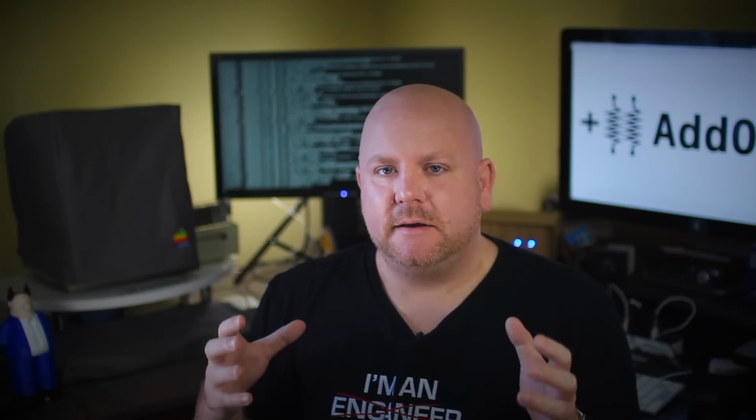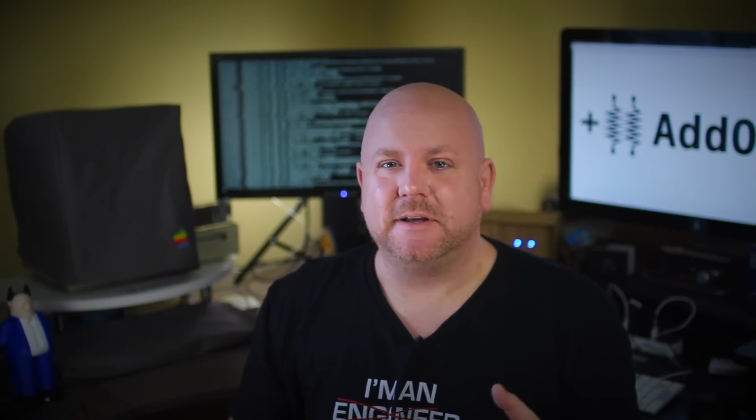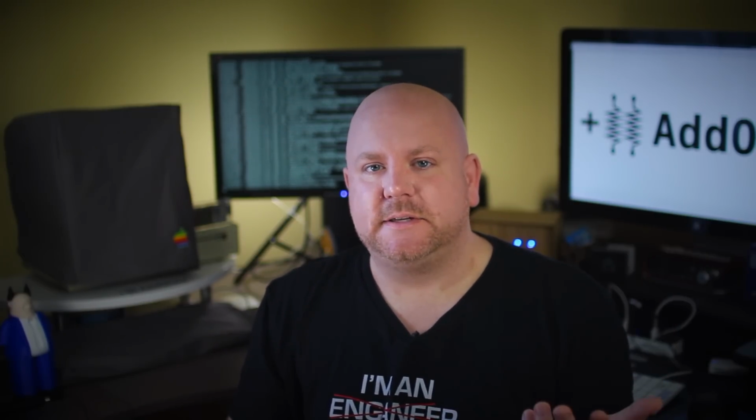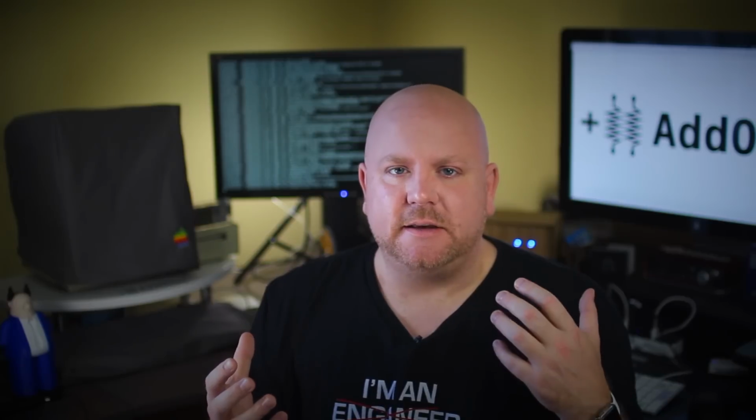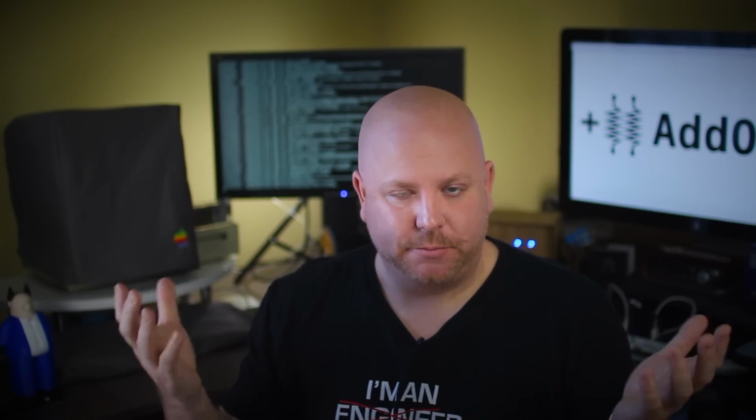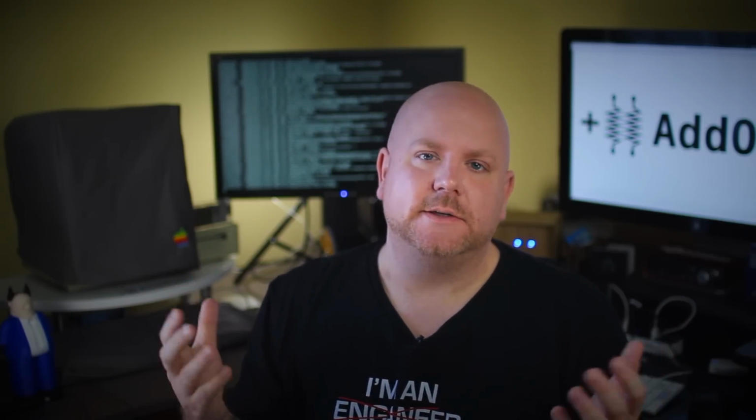Now, in my parts kit, I typically only keep 2 linear regulators, a 7805 or a modern equivalent, and an LM317, or again, a modern equivalent. And that's because with the 7805, I get 5 volts, super common. And with the 317, I can configure for any other voltage. So I don't need to have like 10 different regulators sitting around in my kit.